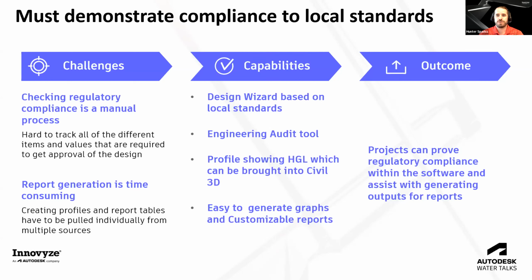From my experience, Midori and I have actually talked about this a lot, making sure you're having those compliance, putting together the drainage reports, and all those appendices can be very time consuming, bouncing between different softwares, trying to pull that information in. And within InfoDrainage, you have the ability on the initial side of the design to use what's called the design wizard to size pipes, set slopes, size your manholes based on local standards, so that you know in the beginning your design is set up to meet those slope and size requirements.